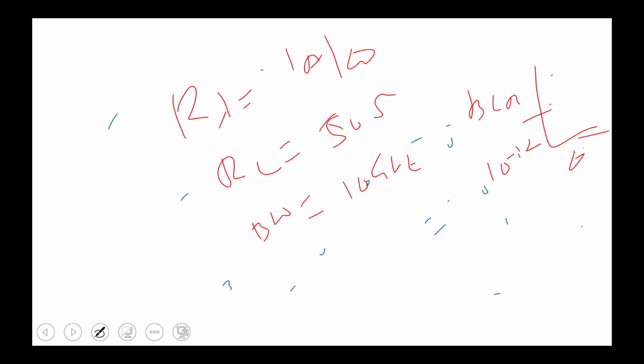Correct. From that graph, previously I explained that bit error rate graph with the quality factor. So you have to take the quality factor as 7, and I think that value of the bit error rate is around 10 to the power minus 12. Okay, so in the case of considering zero power, the quality factor we have defined as I1 upon sigma 0 plus sigma 1.